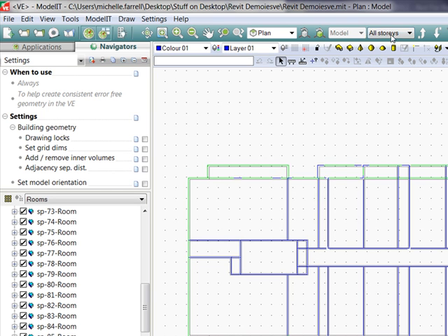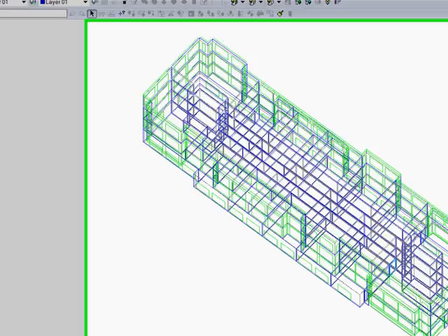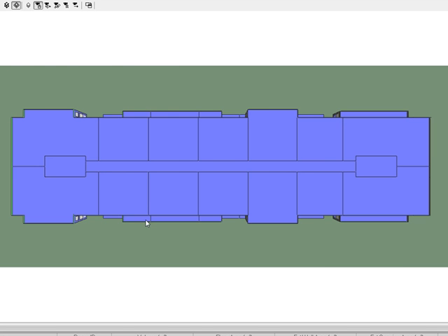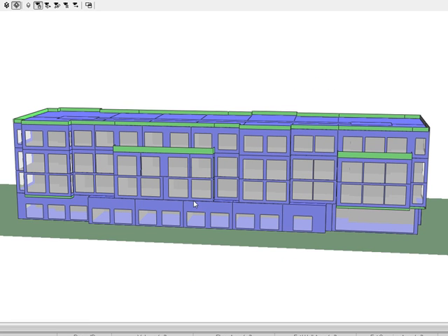Okay, so just to look at this building, I'm going to actually go down to this drop-down menu to rotate it to an axonometric view, and then I'm going to pull out my preview. When this comes up, I'll see the exact GBXML that I translated in, and I'm going to see that my spaces are showing in blue, meaning they're a room, and things that are not connecting to a room, not an air-conditioned or occupiable space, are going to be showing in green.